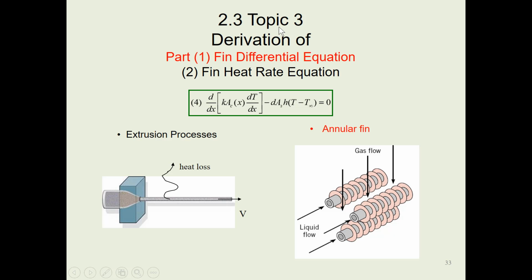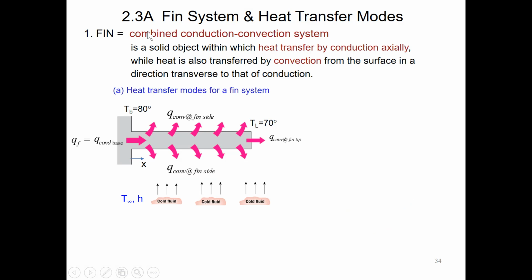Welcome back. Topic 3, Part 1, Derivation of fin differential equation. A. Fin system and heat transfer modes. First, a fin is a combined conduction and convection system. That is, conduction is going through the fin, while convection is between the fin surface and moving fluid.